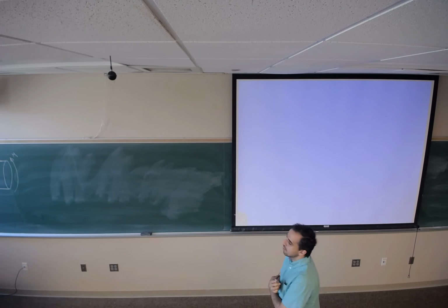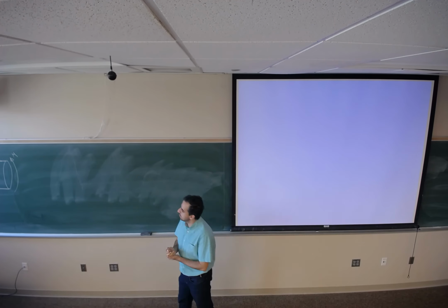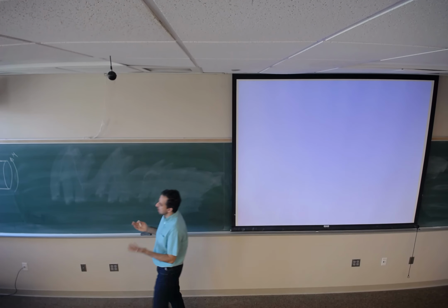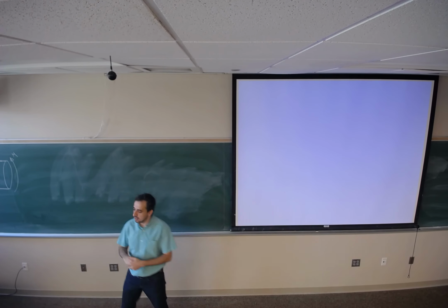If I ask you to do the stress analysis for this, first you need to find the critical section if the shaft is not moving. So we don't have any rotation on the shaft. You should find which section is gonna see the maximum stress. The only load that you can see here is a bending moment.